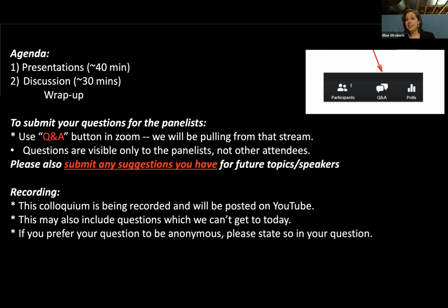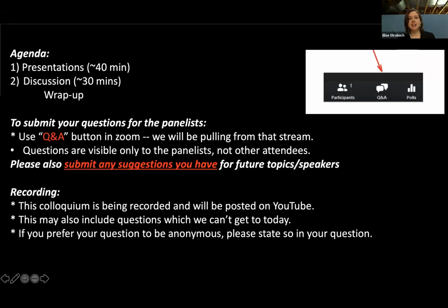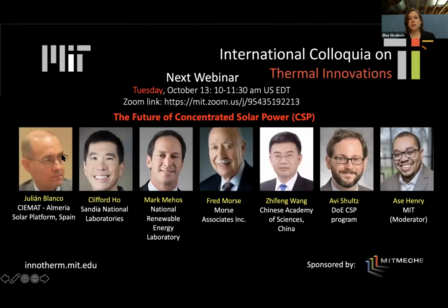But then the third thing is that with windows, it's not just through the frame, it's not just through the leaks, it's not just through the glass. All of those things contribute to window losses. So sometimes even just taking a film of thermal insulation and sticking it to the glass isn't actually going to get at the real core of your problems. So I think a huge area that we need more work on is solutions for retrofits for windows. And I'll just make a nod that the DOE ARPA-E project, the SHIELD call, has some really interesting focuses on trying to solve that problem. So hopefully we'll have something soon.